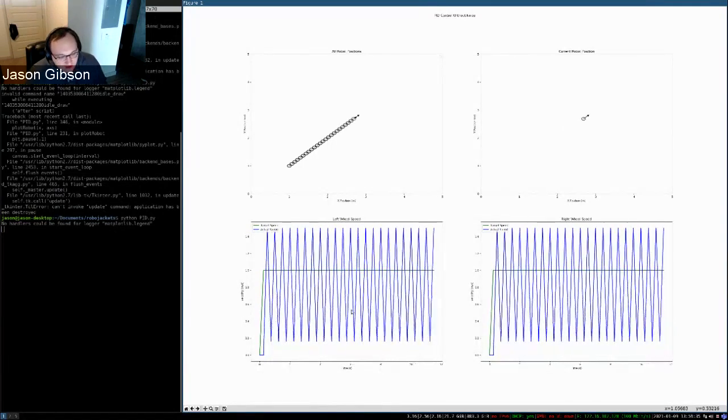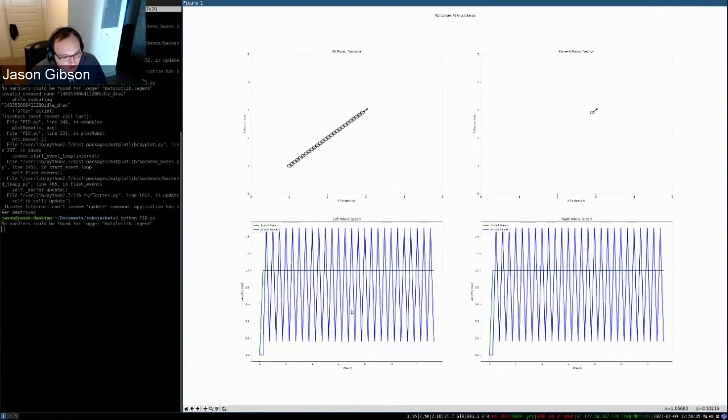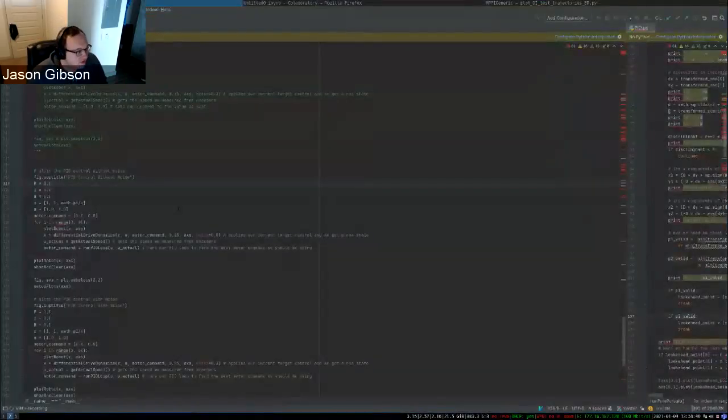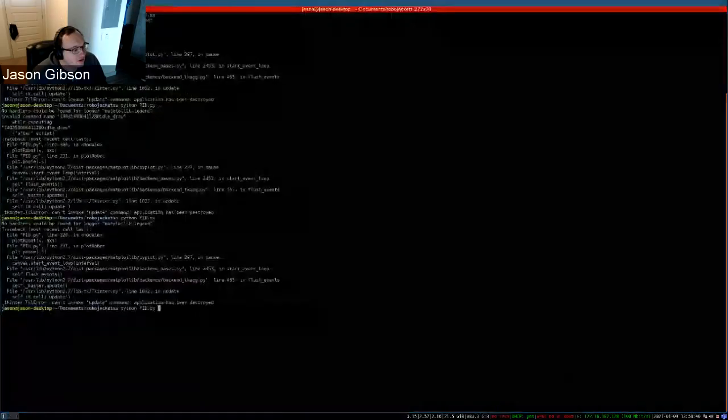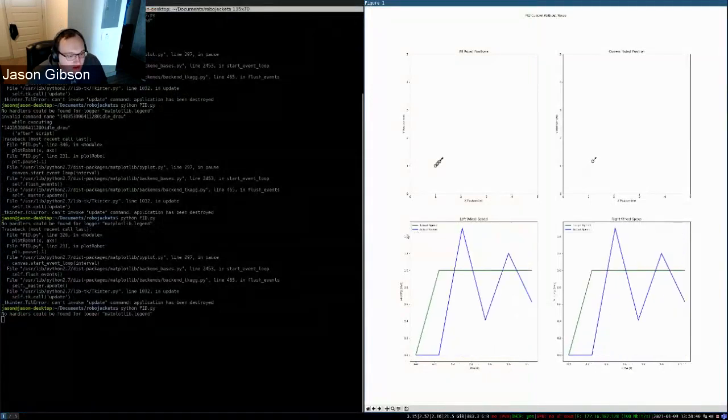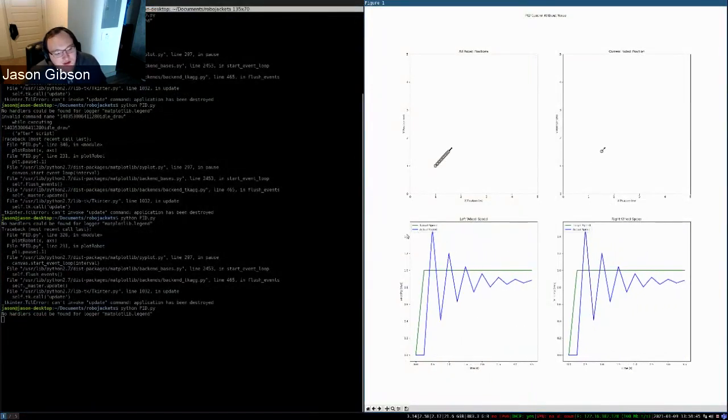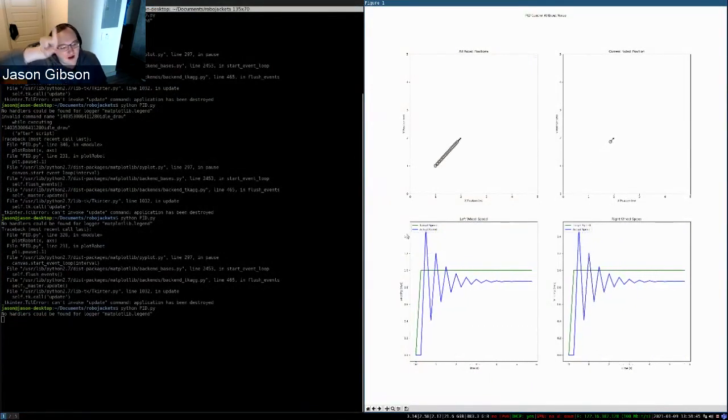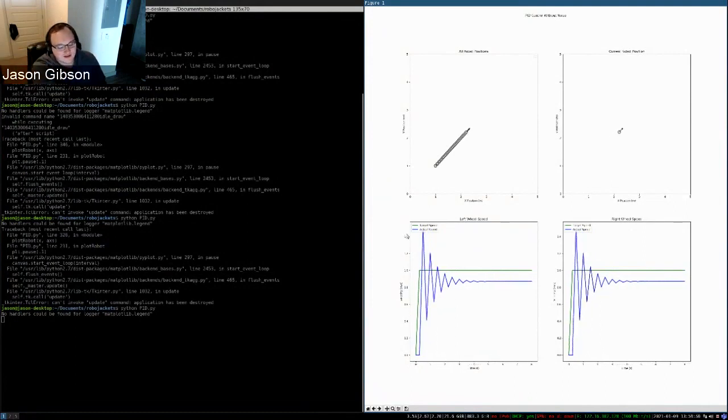actually. So how you simply tune PID is you essentially want to increase your P until you're reaching your set point as fast as you probably want. So I'm going to do 6. So now this is more what you tend to see: it peaks up above it and then you oscillate. So you want this kind of behavior when you do your PID.